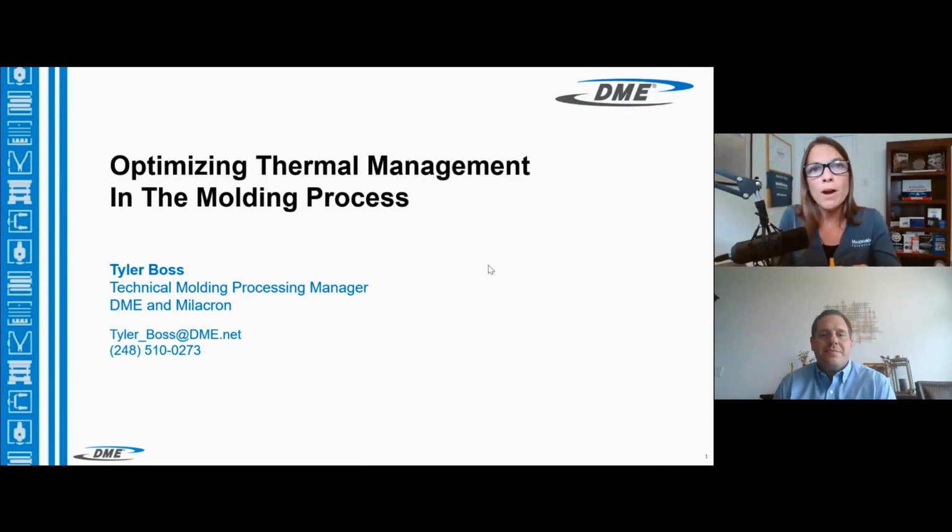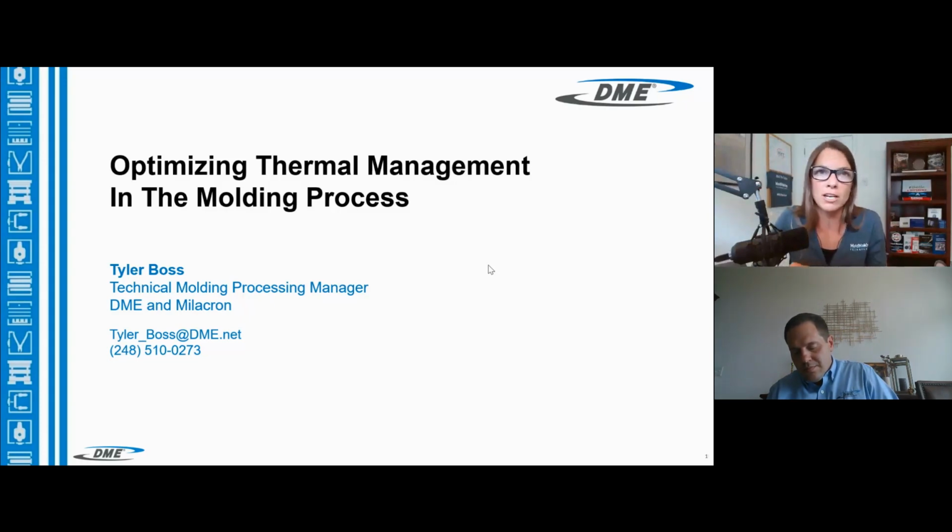All right, Tyler, from the processing perspective, trying to achieve HDT may be considered a waste of time for many people. Is it in general a good practice to manage appropriate heat transfer levels before ejection? I would say yes. I'm not going to say we always did that, but yes, trying to get the heat out of the plastic you're ejecting, a large portion of the heat, and it's material specific. But yeah, trying to get to that HDT is the goal.